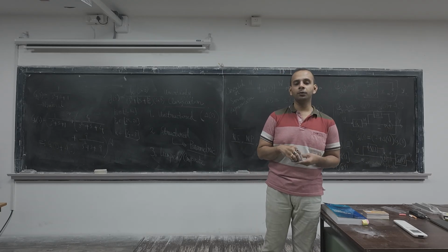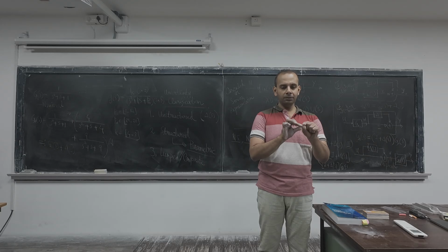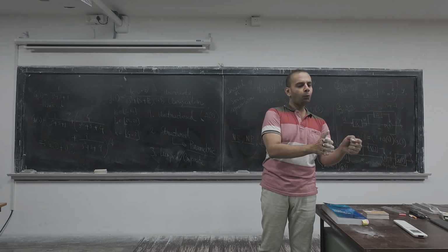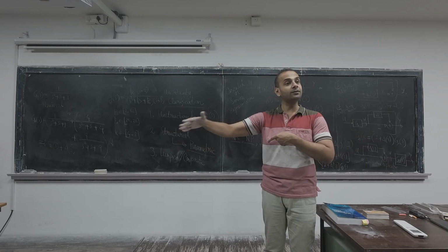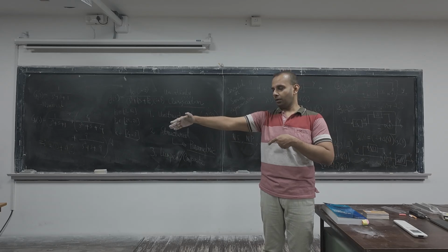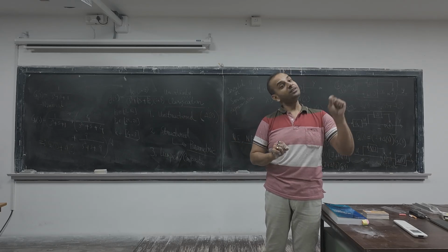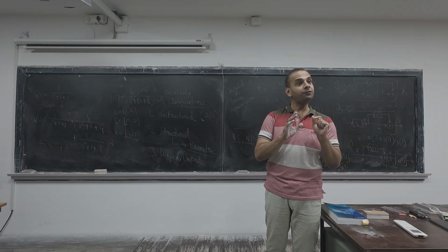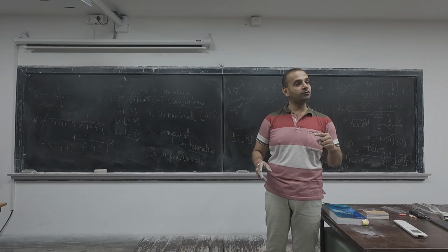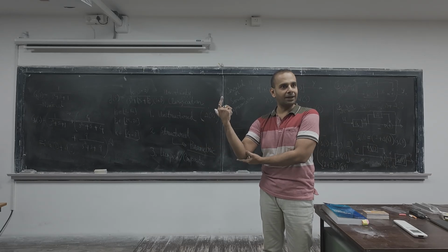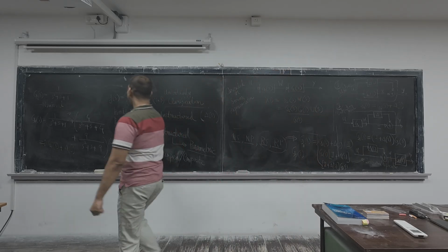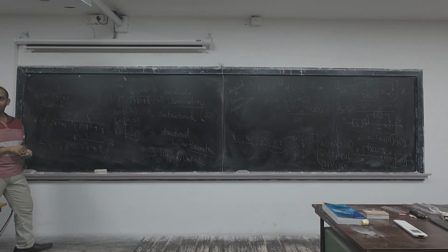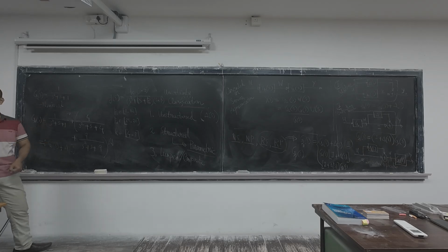Cantilever simply means, suppose you have a very thin aluminium strip that is attached on only one side to a basement, and its length to weight ratio is very high. If you have a structure whose length to weight ratio is very high, what will happen? It will be susceptible to vibration. And then an easy model, called the linear truncated model, is that you go for a frequency domain analysis, because originally it is a distributed parameter system.